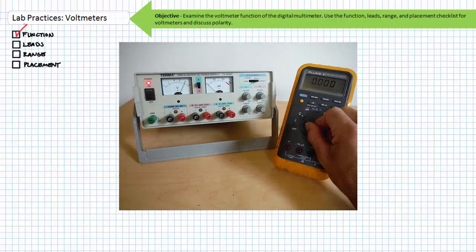Function. First up is our Fluke 87. We'll place it in DC voltmeter mode by turning the mode selector to the V with a straight line over it. Don't get tricked into settling for the modes on either side of DC voltage. The V with a squiggly line is AC voltage, and the millivolt with a straight line over it is for small-scale DC voltage measurements. These aren't the modes you're looking for. You want the DC voltmeter function.